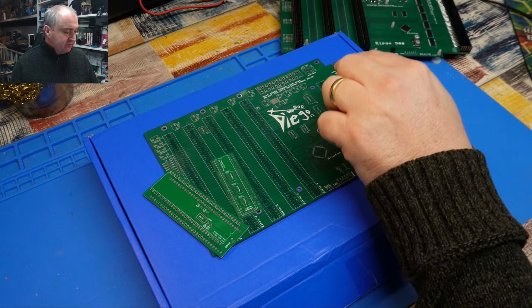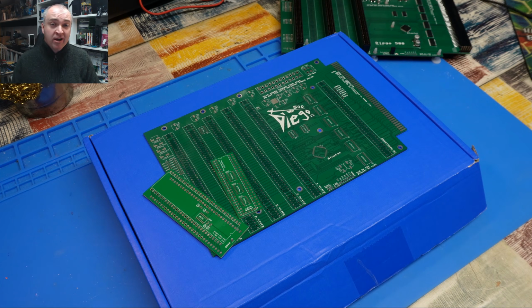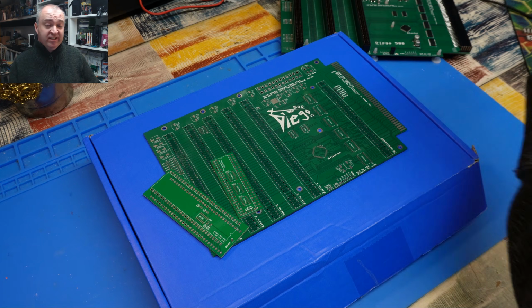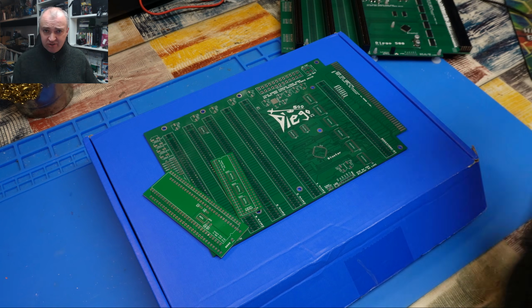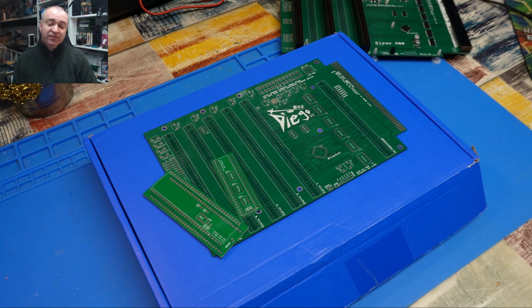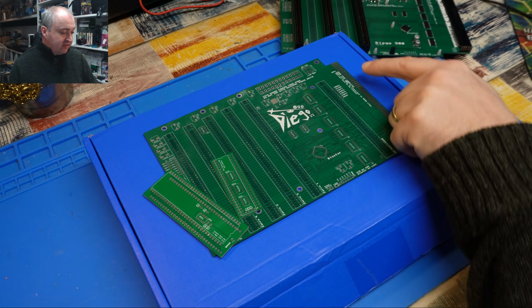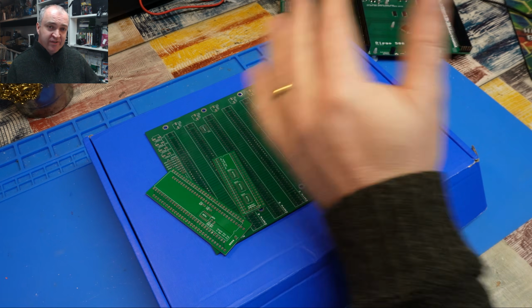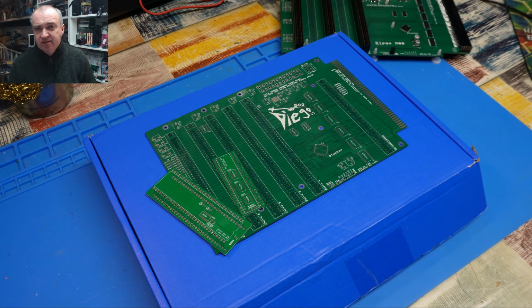But if you had, say, one of Live2's gotta go fast RAM adapters in your A500 underneath the CPU, well, you would need to connect its config out to that config in. Or indeed, if you had anything in that CPU socket on the Amiga, be it the RAM expansion, one of the accelerators, say for example that Spitfire that we built a while back here on the channel, it's got a config out, you would need to connect that to that in to allow the rest of these devices, whatever you may have in these slots, to be configured. So again, only necessary if you need it, but it's there.